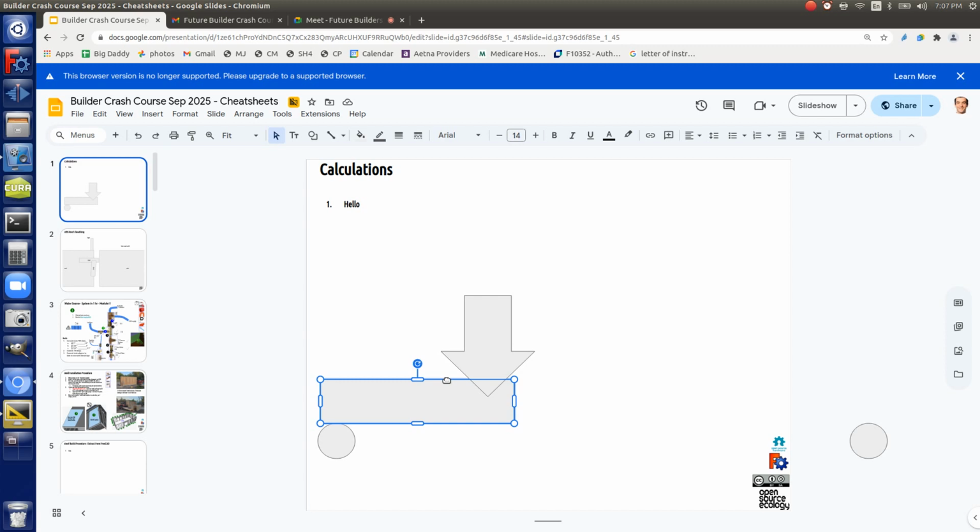And that's why in our design we have an effective span of only 20 feet, because those supports are holding it about 6 feet from each end, so that's 12 feet. You've got 32 minus 12, an effective 20-foot span. So we just reduced that design into 20-foot spans, like the deck. So it's much easier, which is why it works.